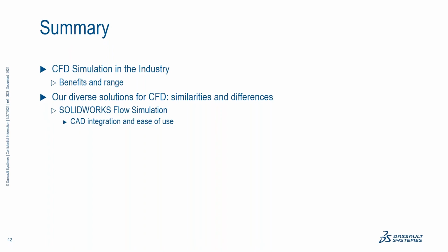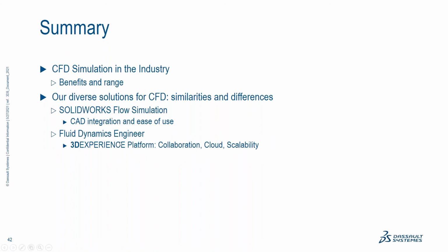SolidWorks Flow Simulation, the biggest advantage is the CAD integration and the ease of use. The fluid dynamics engineer, the biggest benefit is the integration within the 3D Experience platform, and that brings collaboration, cloud, and scalability. Now, again, you can link it to your CAD, but obviously with Flow Simulation being totally embedded within the SolidWorks interface, that's going to be easier. And finally, XFlow with the LBM methodology opens up applications for highly transient flows and moving mesh applications.